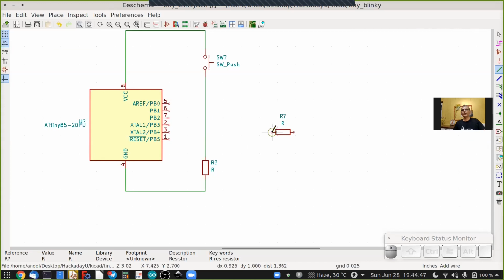Let's also join up this pin of the resistor. Click on this once. Click over here once, and your wire is clear. And as you can see, these two wires have crossed, but it hasn't put a junction over here because it's smart enough to know that you don't want that connected. Since this is going to be going to our RGB LED, which also needs a ground and 5 volts, we probably ought to bring those wires here as well. So we have a nice pin.